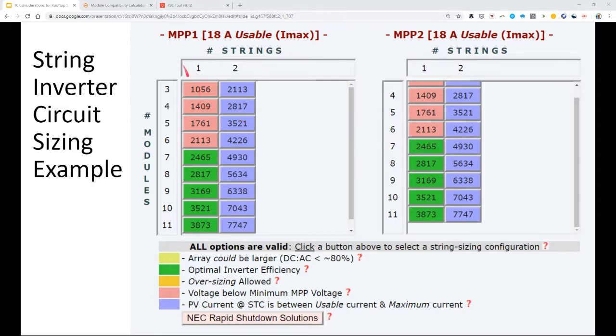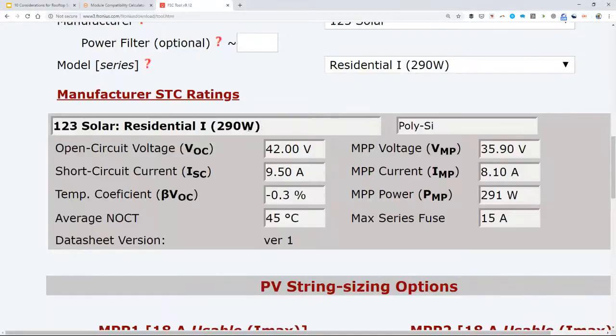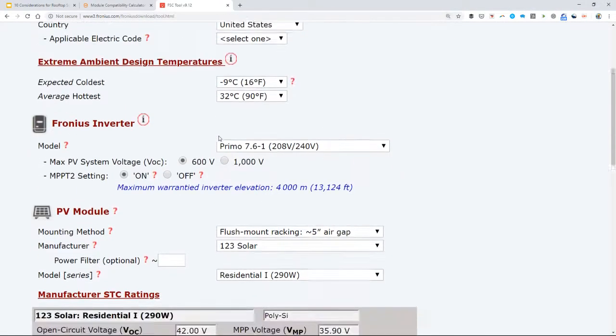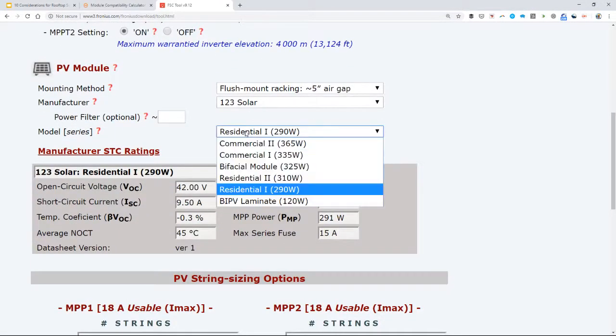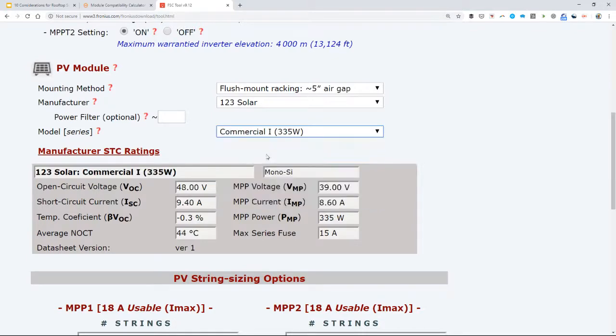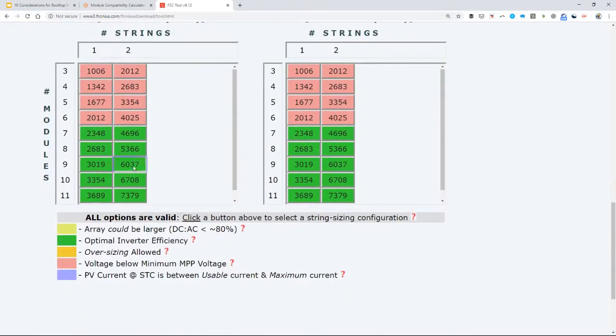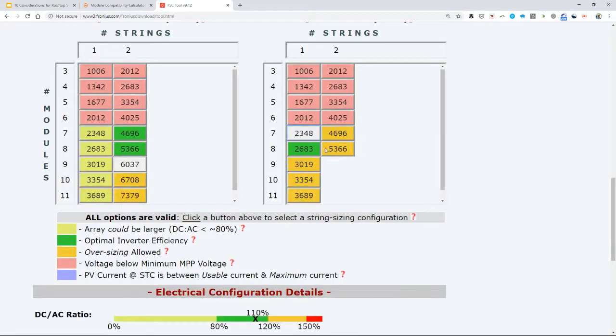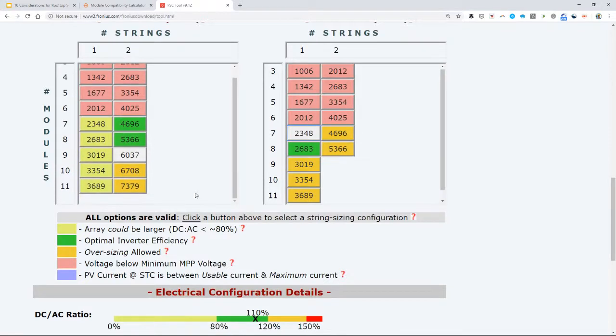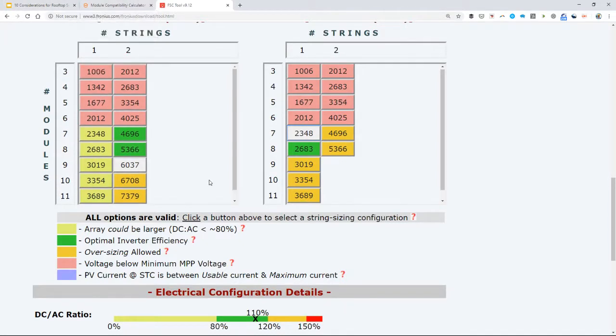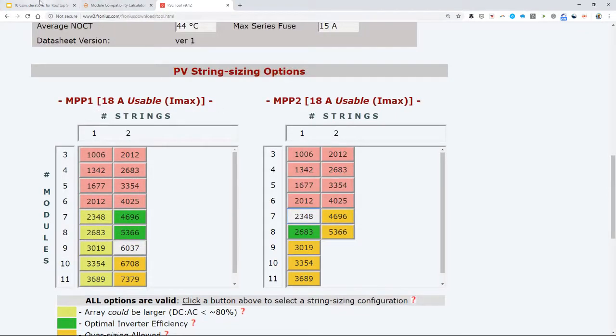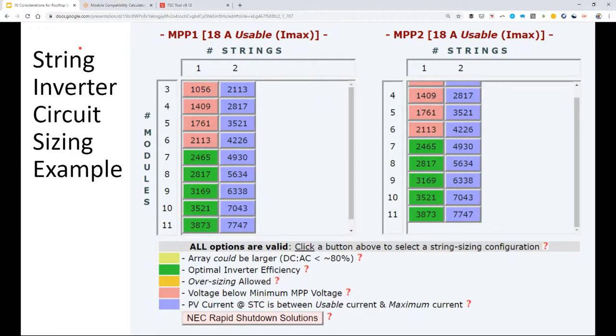Just as an example, higher end inverters have multiple maximum power point tracking circuit inputs, such that shade or mismatched orientation of one string or circuit would only impact that specific string and not pull down the rest of the system. This is an advancement from string inverters of years past, where all of the solar panels on the system had to face the same direction and have the same number of modules per circuit without any shade at all.